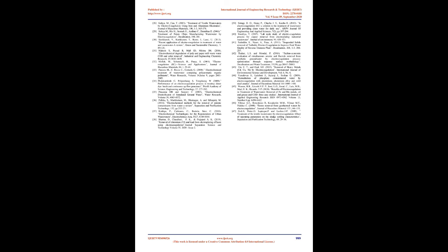Effect of operating temperature. Temperature is another important operating condition which will affect pollutant removal efficiency in wastewater treatment. The turbidity removal efficiency from abattoir wastewater in the EC process increased by increasing solution temperature. The results show that increasing temperature has a negative effect on removal. However, it should be noted that the operation of the electrocoagulation (EC) process at higher temperature significantly reduced electrical energy consumption and fluid conductivity increases. Therefore, the production of hydroxide species increases rapidly, which then enhances the pH value. Yilmaz et al. 2008, Kittel et al. 2011, Vasudevan et al. 2009.